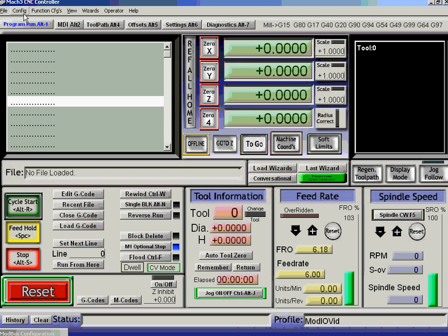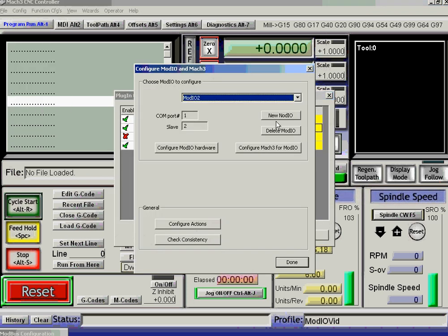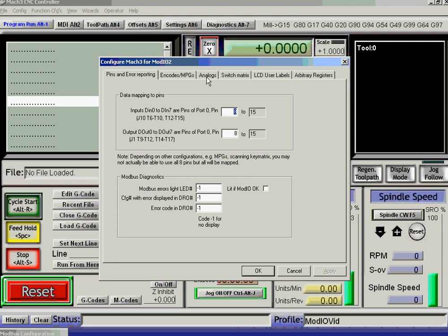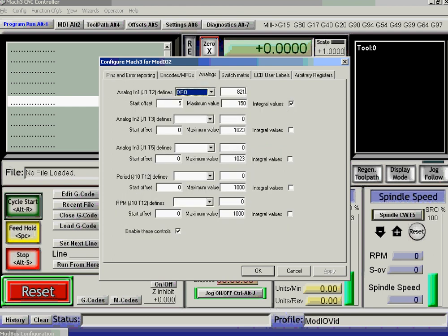One of the other good things you can do with an analog input is you can configure it so that it is integral values, and if you put the value into something like the spindle pulley number and have a multi-position switch with 4 positions, say, and 4 resistors that give you 4 inputs, you would then choose an offset which went from 1 up to 4 and have integral values, and adjusting the switch, or a potentiometer, come to that, would set the pulley number to the position of the switch or potentiometer. So that's quite an easy way of interfacing to select multiple pulleys.